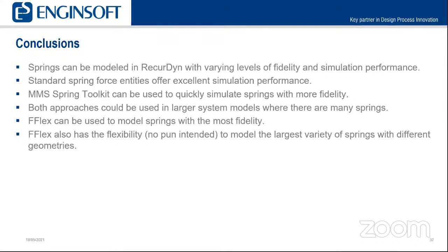First one being for the FFlex valve spring, how was it constrained in the model? Sure. So that was constrained with contact between the spring and the bodies above and below it. And then there was also used what's equivalent to a Nastran RBE3 element, which is sort of an interpolation element that was used to keep the spring from drifting off center. So the master node for that RBE3 element was constrained with an inline constraint, sort of vertical, to restrict the motion to vertical motion only. And then the slave nodes were then sort of the bottom surface of the spring.